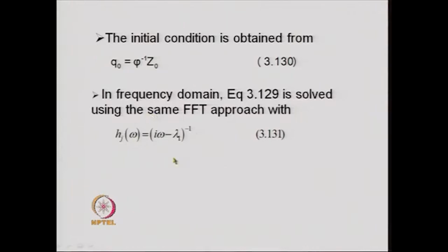So, that also has been discussed before while solving a state space equation for a single degree of freedom system. And in the frequency domain, as before, we use the FFT algorithm, that is we first find out the frequency contents of the response by multiplying H(j omega) with the frequency contents of the load,